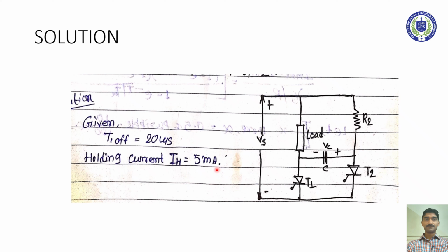You must know the basic things, because a thyristor, as we all know, is a 4 layer, 3 terminal, 3 junction device, and the current associated with its turn-on process is the latching current, and the current associated with its turn-off process is the holding current. Considering the idea of such basic things, moving forward to the explanation of the numerical, as far as the figure is concerned.